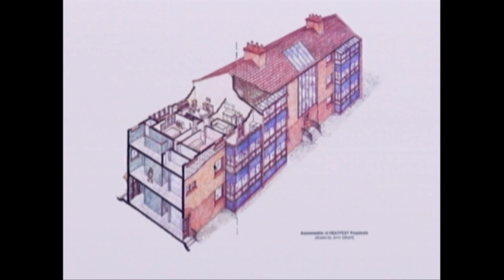So the U value of the window in those locations was 3 or 3.2, that sort of order. Compared with if we were designing, for example, to German passive house standards today, we would go for 0.8, so huge difference. The walls we had at 0.25, again, if we were to passive house standards today, we would be going for 0.1 or thereby, but that's relatively easy to upgrade.